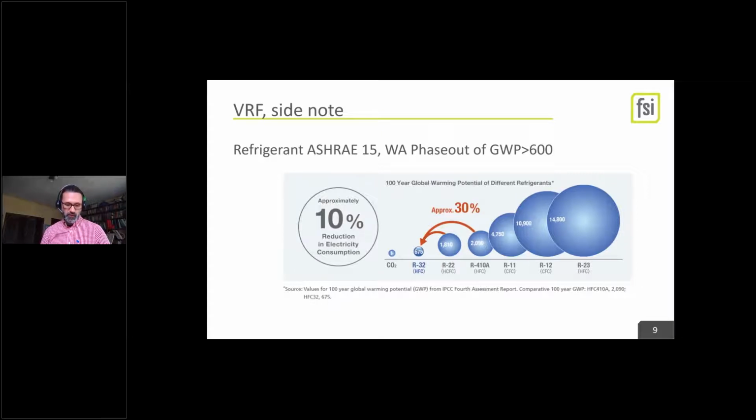And in Chapter 5 of Washington State Energy Code, this is new news. This happened, I think, Duane, a couple of weeks ago, that the State Code Council adopted the recommendations of the advisory group and are going to have an all-electric provision for new buildings again, but also Chapter 5 for alterations is going to push you into electric buildings, except some pretty broad exceptions. So added electrical service where it's infeasible, where you've got existing hydronic systems. There's some pretty big holes in the Washington code. I think that was the whole picture.